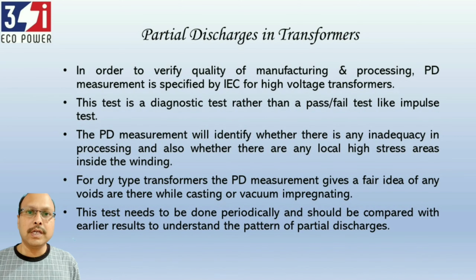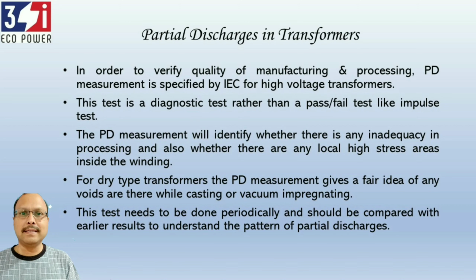Now, in order to verify the quality of manufacturing of a transformer, standards like IEC and IEEE specify a partial discharge test. These tests are not routine tests, they are special tests, more like diagnostic tests.